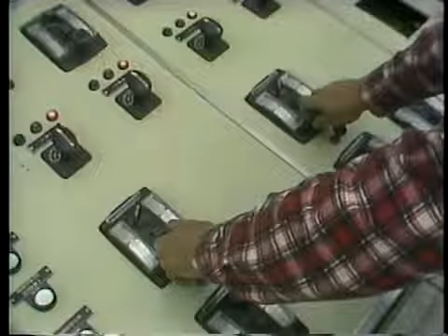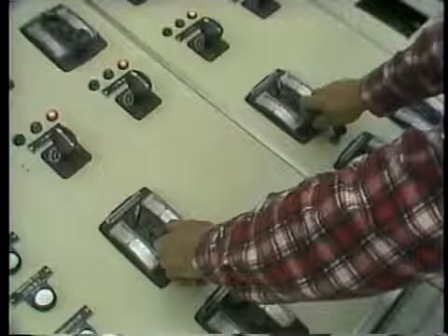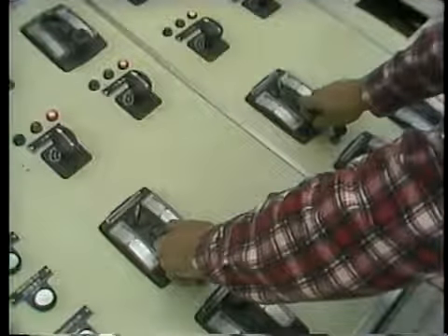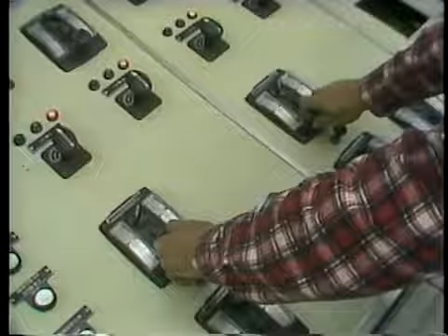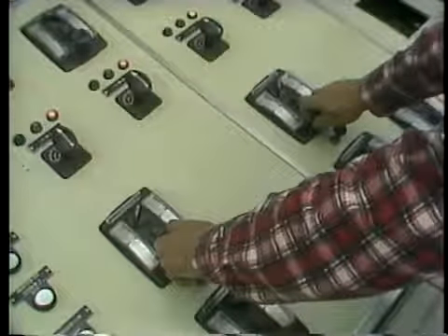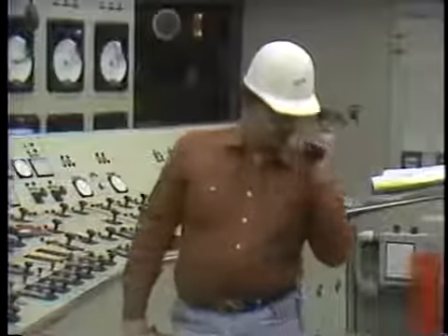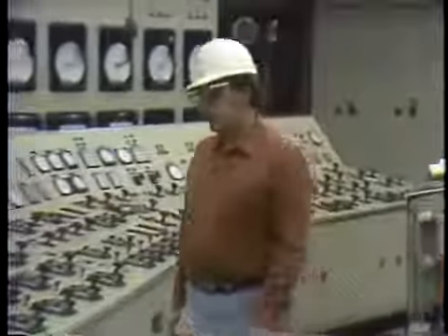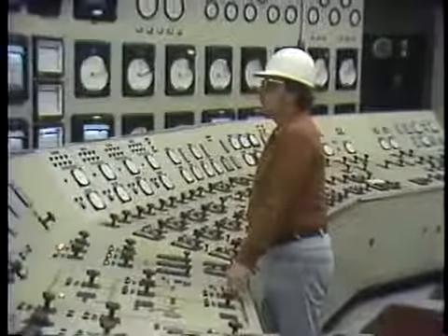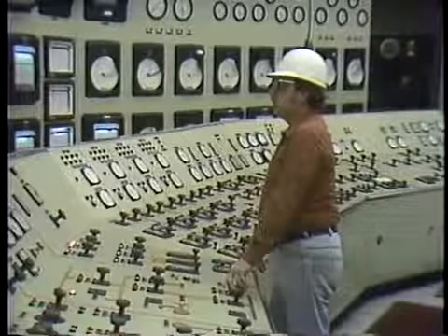Most procedures will require that the operator isolate the defective fan and immediately reduce the flow rate of fuel and air to rates which can be handled by one ID fan. This means that steam flow, feed water flow, and condensate flow must also be reduced. Once the load on the unit has been reduced and stabilized, the operator should immediately inform the shift supervisor and load dispatcher. If conditions allow, the operator should then try to return the unit to normal operation.